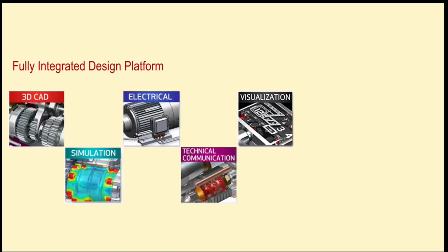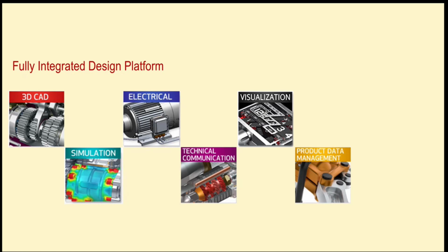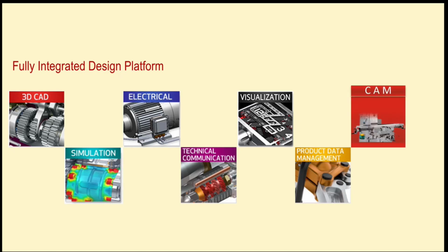That's the important thing. Next, you have product data management. If you are working in teams, you can use product data management. It is SolidWorks PDM, which is a separate added application. So you can easily create revisions of your work. You can set up vaults, who is logging in, who is logging out, what time period is allocated to them. So everything can be managed in SolidWorks PDM, that is product data management, which is a lifecycle management tool.